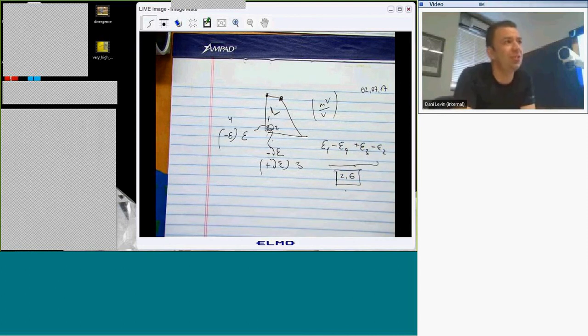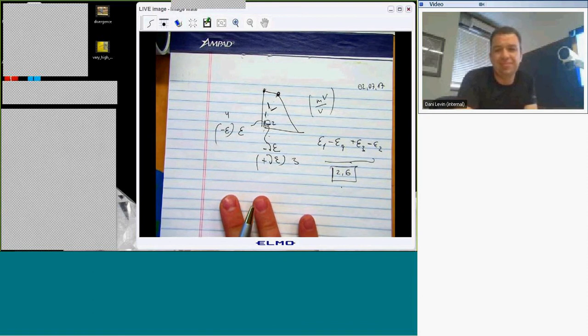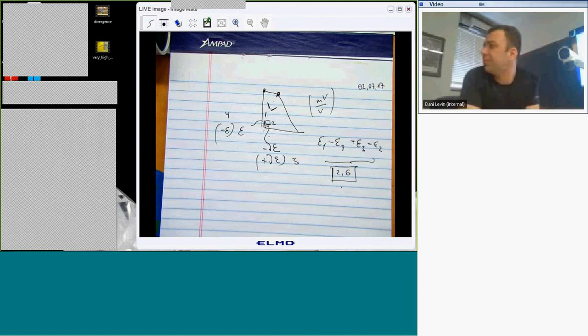It's also a matter of robustness. The things that are survivable in a wind tunnel may not be survivable in flight. And even in the wind tunnel, it depends on whether you're doing a low speed test, as we're going to be doing, or whether you're in a transonic or supersonic tunnel, where the flow environment is harsher. Instrumentation that you might use in a low speed test might not be suitable. Also, in transonic flow, you're much more concerned about any instrumentation disturbing the flow. In the low speed case, if you disturb the flow a little bit, it probably doesn't matter all that much.